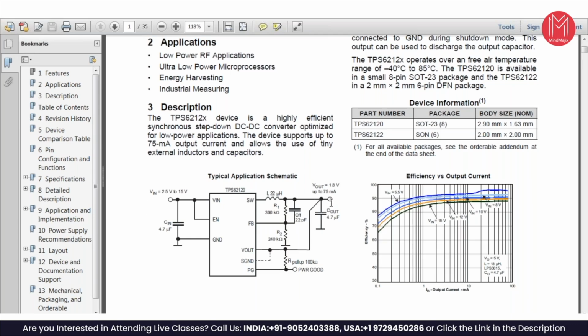Also, if for whatever reason a component suddenly draws more current and later doesn't draw the current, these capacitors are added to ensure those fluctuations do not create noise, because it's a network of connections. In those connections, when the current flows, there is a chance that we generate noise. So this decoupling capacitor always needs to be as close as possible to the pin.